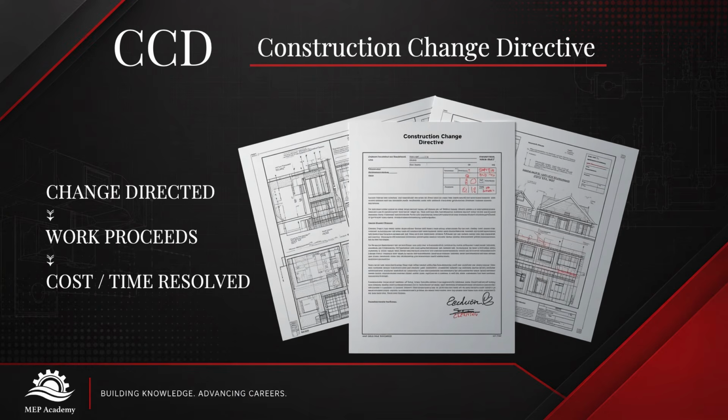Number 52. CCD, Construction Change Directive. A CCD directs a change in the work before the contractor and owner have necessarily agreed on the final adjustment to cost or time. It allows necessary construction work to proceed while those impacts are resolved.